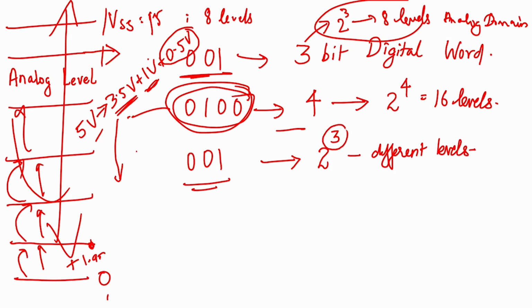So, this 3 is very significant, 2 raised to 3 levels, correct. So, then that is how you will convert this digital signal to analog. This is like the 0th bit, each bit is 0, 1, 2, clear, correct. That is how it is 3 levels. This is the 0th bit because it is changing every time, right, that is fine adjustment. So, that is 2 raised to 0, this is 2 raised to 1, this is 2 raised to 2.